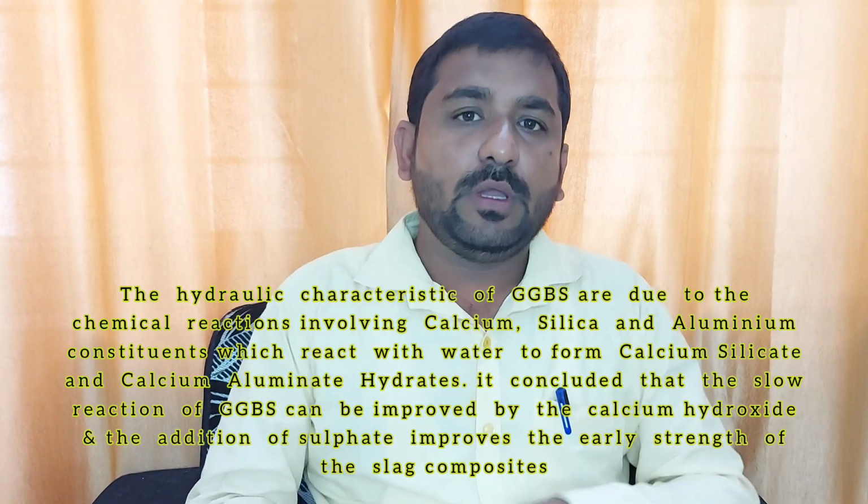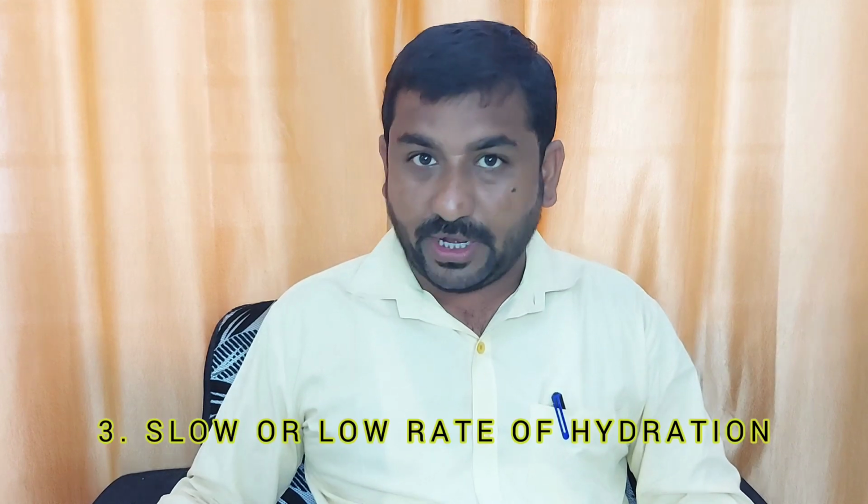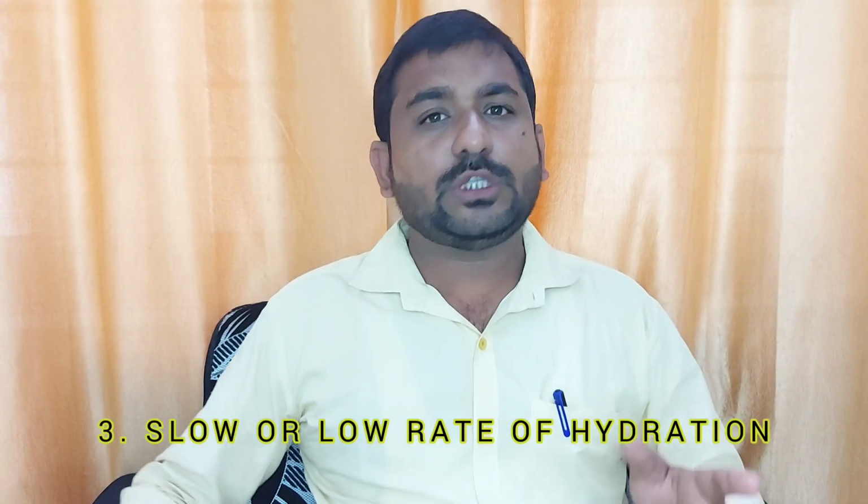That's why I said 100% replacement is not possible in a general way, unless you provide supplementary alkali activators to the GGBS. If we replace a high volume of GGBS in day-to-day commercial life, what consequences and issues do we face? Generally we face slow setting, slow strength development, and a slow rate of hydration, which causes a lot of effects.